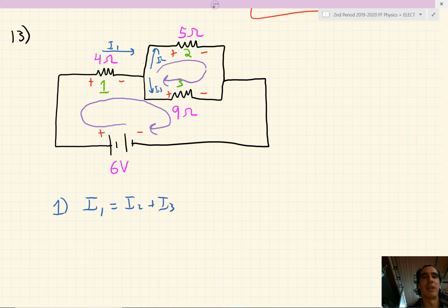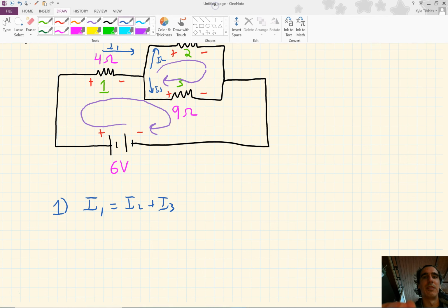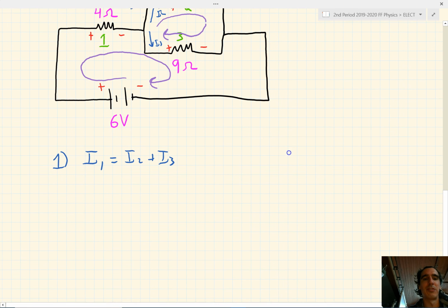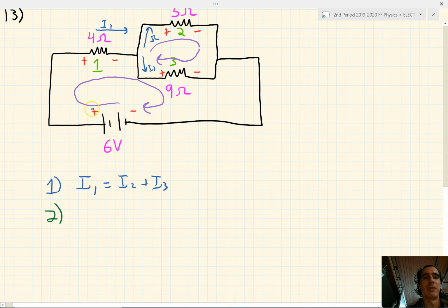The second thing that we know is we could use Kirchhoff's voltage law, or KVL. If we look at our first loop, we could see that the sum of the potential differences add up to 0. So if we go through V1, notice it goes through the positive then the negative, trace it through, plus V3, minus, as we continue following it to the battery, it hits the negative, so minus VT is equal to 0 volts.